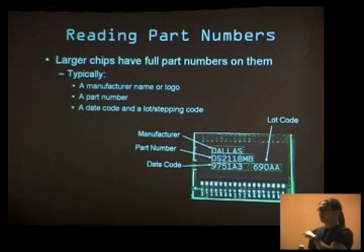A lot of times I use the date code to identify the age of the hardware. So you can say, generally I'm looking for technology in the 0.25 micron domain, so I can narrow my search space for what kind of stuff I'm looking at. So that's actually a really useful cue.